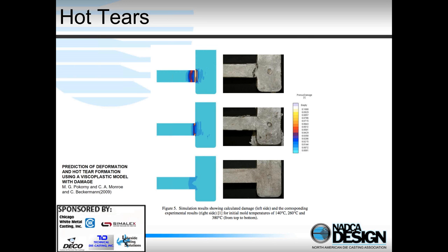Shrinkage porosity causes contraction, develops stresses. We're casting in a metal mold, so the casting is going to give well before the mold gives, and therefore we can pull the casting apart if we design it really, really badly. So again, if I understand shrinkage and porosity, I can also understand how hot tears and hot cracks form in a die casting.